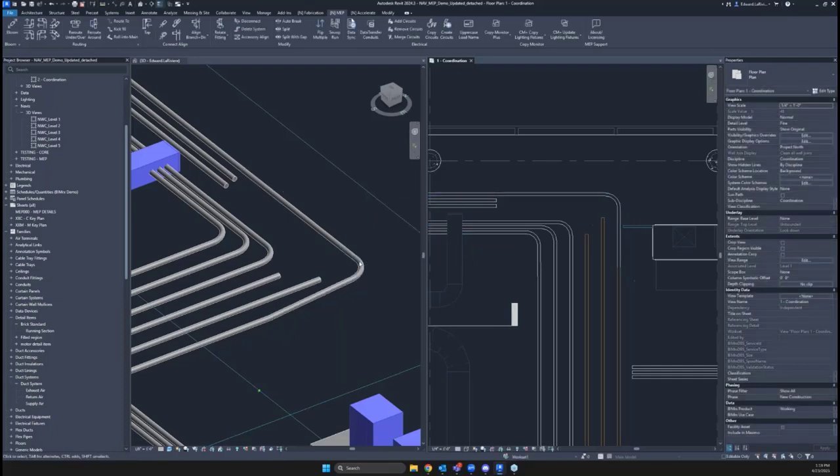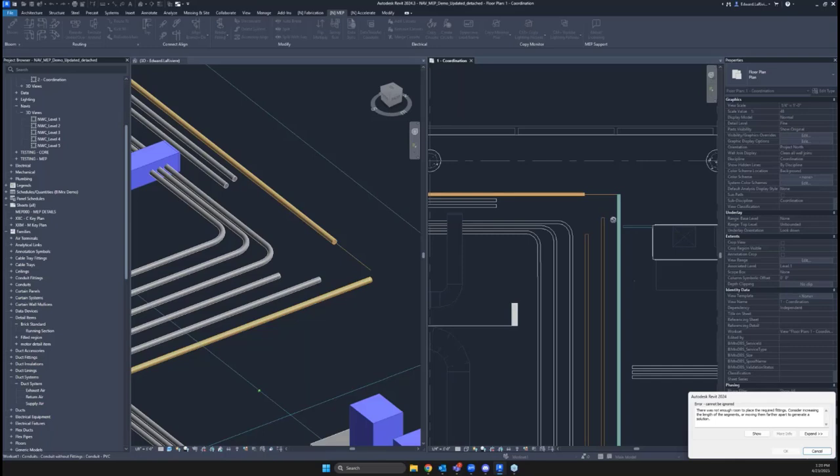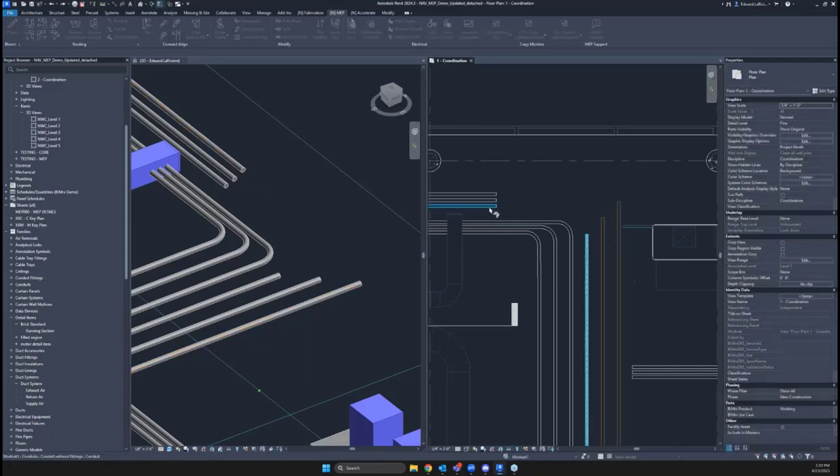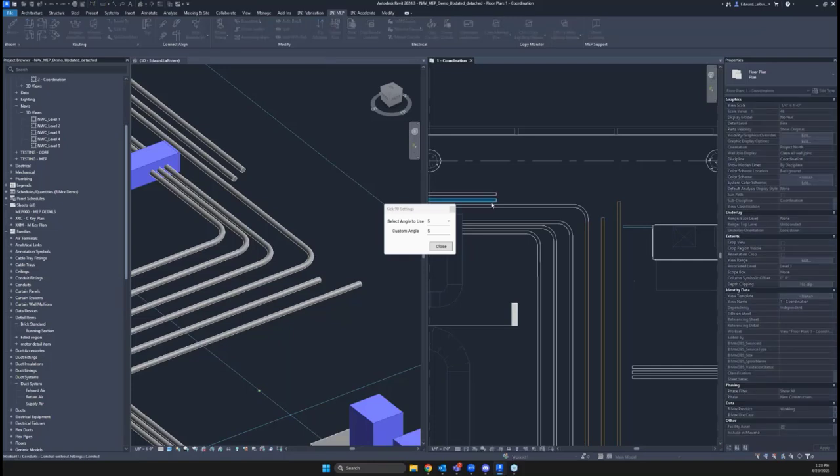And tools like this exist because Revit can't handle it. If you try to trim that corner using the classic trim tool, Revit just can't do it. Trim is only good for elements that are at the same height. So where Revit fails, that's where Naviate starts to begin. That's what we want to pick up and make work properly. And we really try to make all these tools dirt simple and feel exactly like Revit. So where trim is click, click, and it brings it together, what do you know? Kick 90 is also click, click, bring it together.